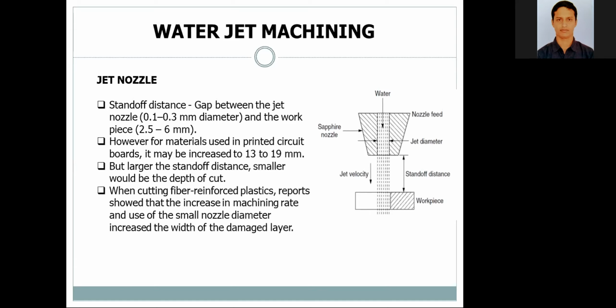Depth of cut is the thickness of the workpiece or the depth we want to cut on the workpiece. When cutting fiber reinforced plastic, reports showed that the increase in machining rate and use of a small nozzle diameter increase the width of the damaged layer.